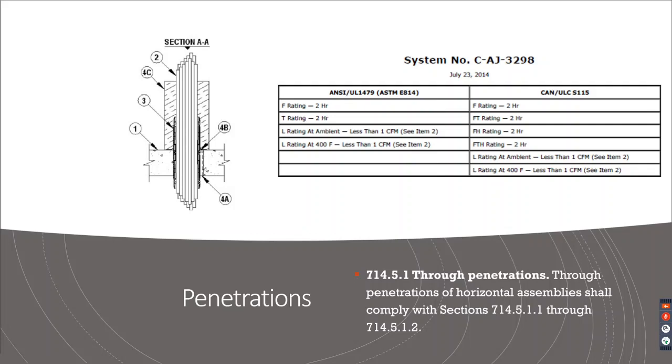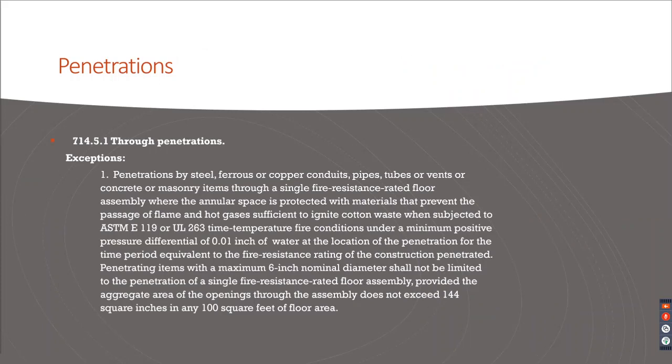The L is the leakage rating that's required for smoke barriers, and even though a smoke barrier is a smoke barrier wall, a smoke compartment consists of the walls and the floor ceiling assembly above and below. So it's the whole cube. So that's part of that, it also needs an L rating. Oh, we talked about that before. We'll talk about it again.